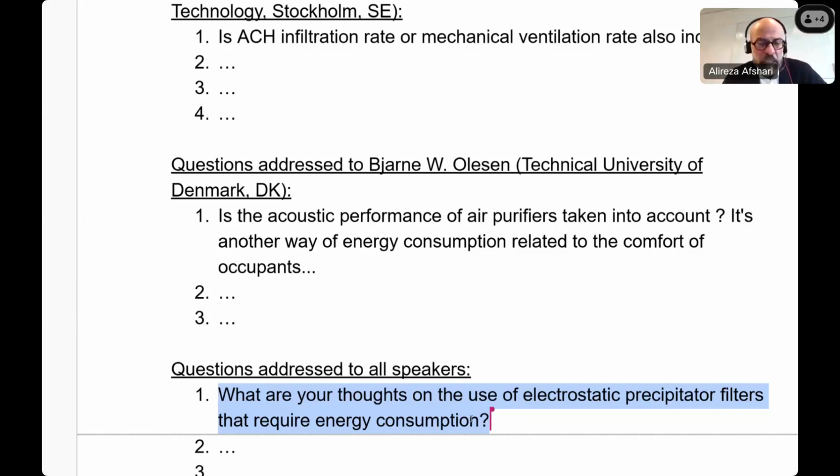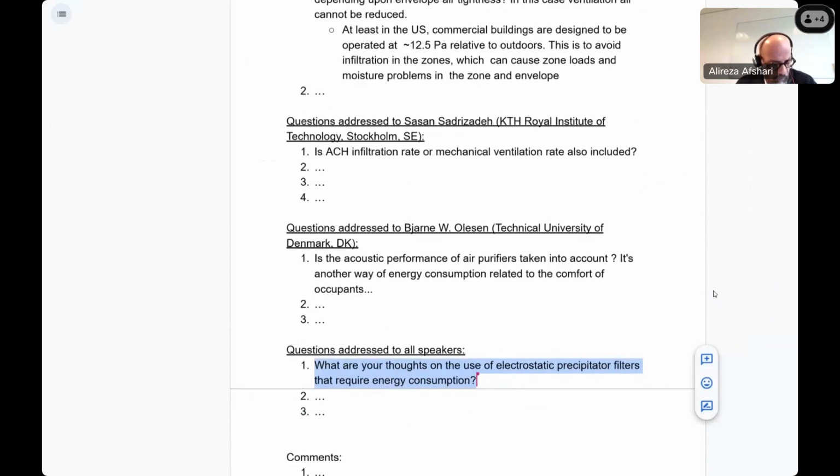Yes, exactly what you say, that's totally correct. And I know that this kind of air cleaner is efficient for particles. But you have to remember, for all air cleaners, when you connect it to power, if it is over 5 kilovolt, it makes generation of ozone in the room, and many people call and claim that they have health problems.